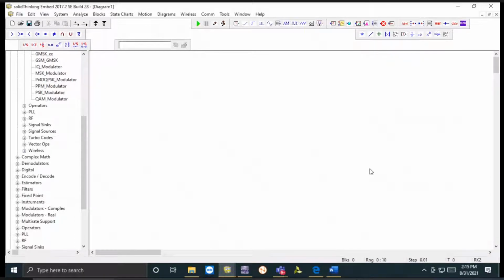Okay, so now we are going to start signal sampling and reconstruction. Basically, we have three methods of sampling: natural sampling and flat top sampling, and sample and hold we are using, right? And for that, we have to keep in mind that the Nyquist criteria should be satisfied.